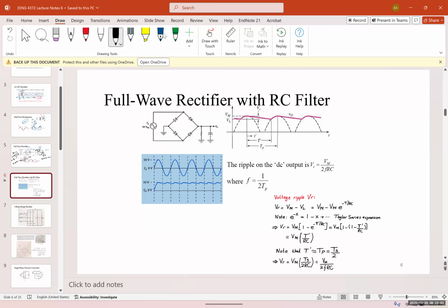So initially, the capacitor is empty, it starts to charge, and when it's fully charged, because this is a large capacitor, it takes time to discharge. And by the way, this is our input and the output of the full pulsating is this black one that I'm drawing. At the next cycle, it's fully charging and wants to discharge, but you're going to charge it again at the next cycle and the next cycle and so on. And you get the bottom graph. You can see.